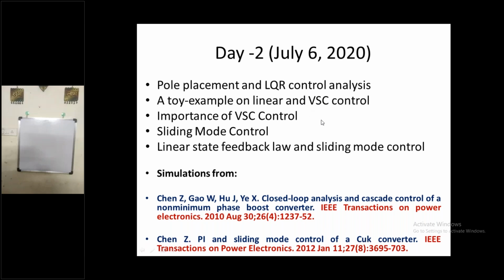We took the example of a double integrator plant, and we saw that if you use either of two different linear controllers, it could not stabilize: from some initial conditions it does not come back to the equilibrium point. However, if you use those two controllers together by changing the structure, which is called variable structure control, then from any initial condition it is possible to bring those initial points back.